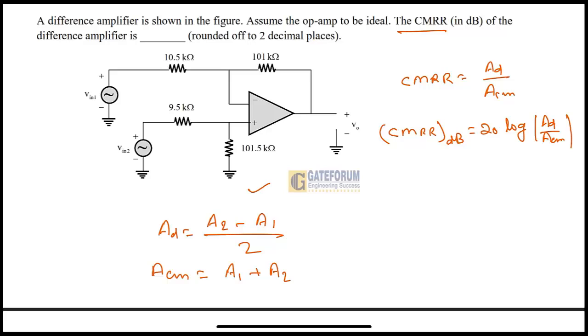Whenever we are considering Vin1, at that time Vin2 should be taken at ground as per the superposition rule. So whenever more than 2 sources are acting at a time, if it is a voltage source, we have to keep the other voltage source shorted, so that there is no current or response obtained due to Vin2 whenever we are considering Vin1. So due to this Vin1,